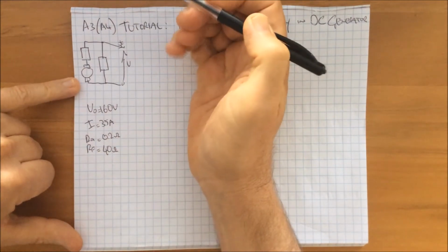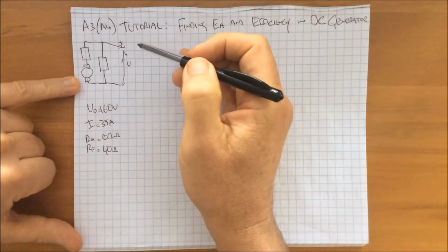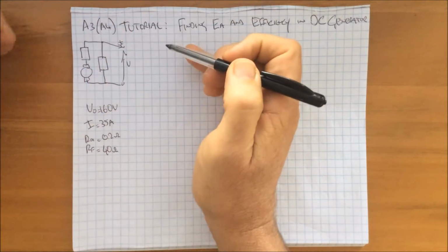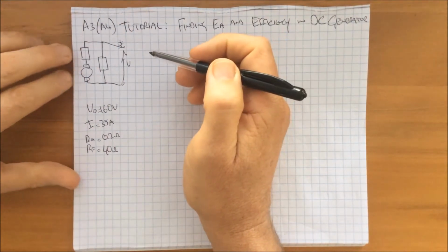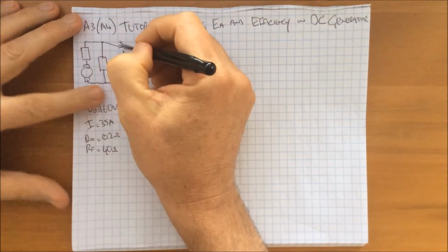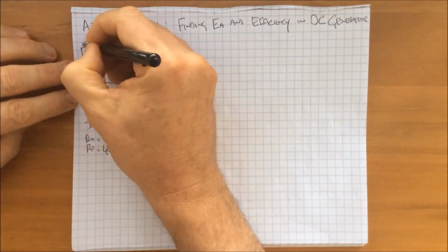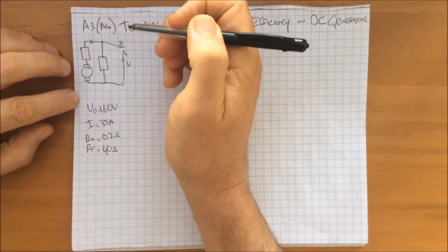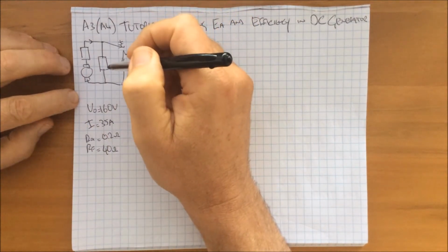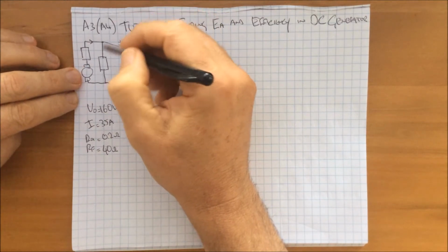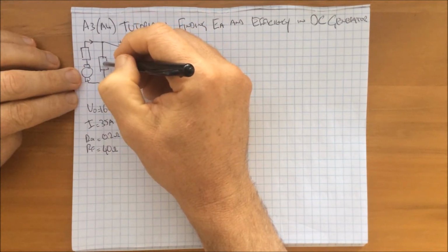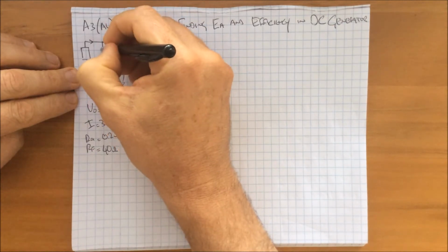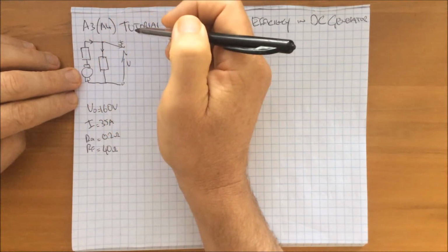We tend to draw it that way around because often we show power flowing from the left to the right, and this helps. So we'll have a current coming out this way. Our generator is going to be generating a current coming out of the armature, flowing that way. And in order to excite this, we need a current flowing in the field, and that current will flow to create our field like this.